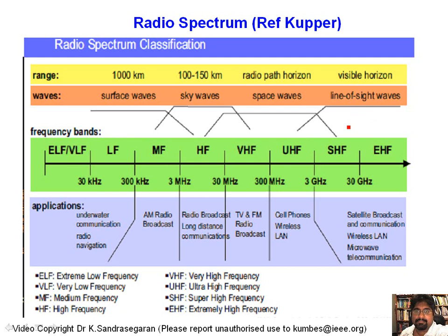So this is probably a disadvantage. You'll notice that when you drive on a road out of Sydney, you see towers on top of mountains, and those towers have microwave links. You will see towers approximately every 60 kilometers or so, so that a line of sight path can be established. So there is a need to place repeaters if you want to build a line of sight path along the surface of the Earth, because the Earth's surface is curved.